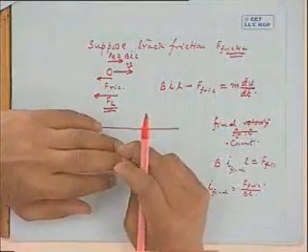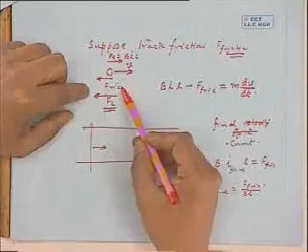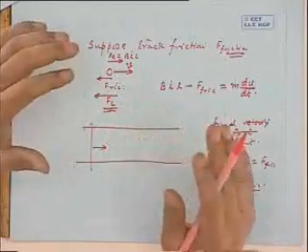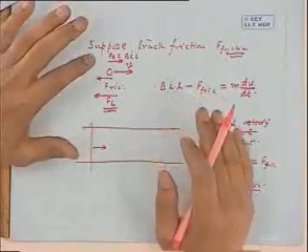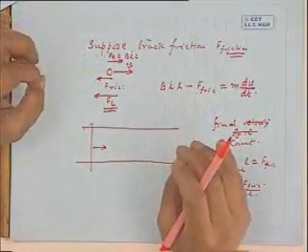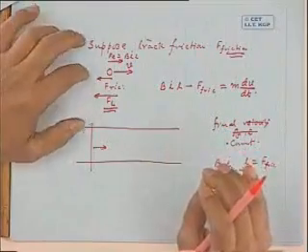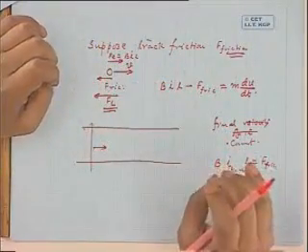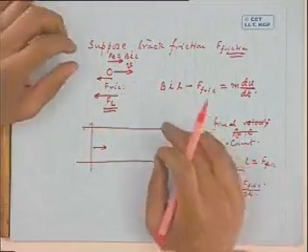That is, the load should impose a force in the opposite direction of the machine. So if you want to put more force in a direction opposite to that, the motor gets loaded. How? If this opposing force is now increased, the speed of this conductor will further decrease to accommodate enough current to make F load plus F friction equal to your BIL. Are you getting? That way this motor will get loaded.